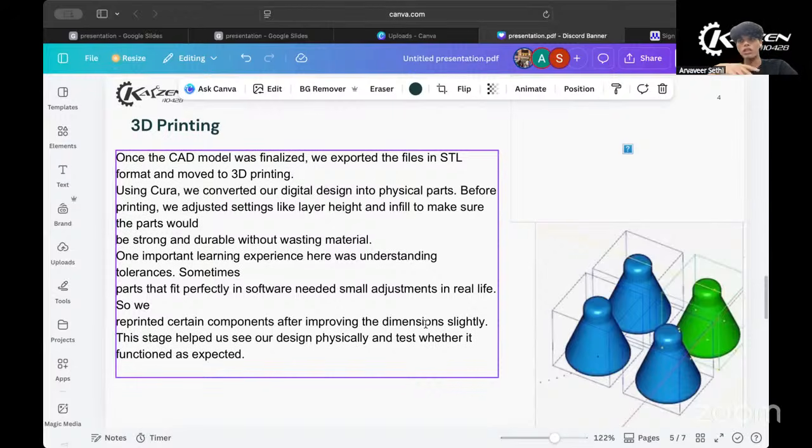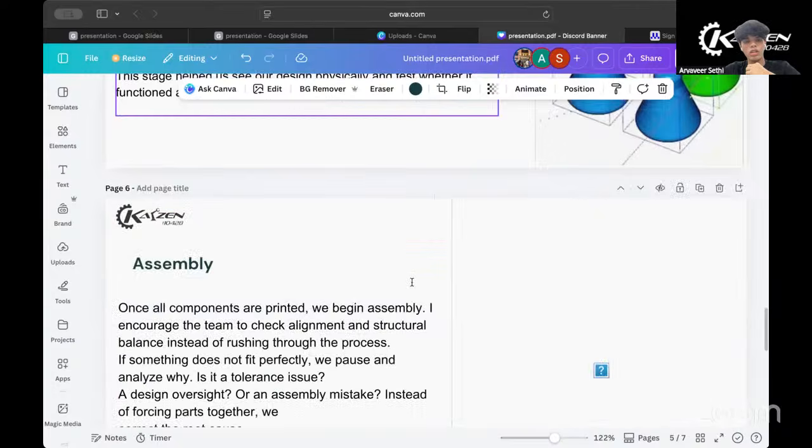Another thing you can customize is the pattern of the infill. You can have hexagonal patterns, net patterns, tetrahedral patterns. Each pattern has a different use. For example, hexagonal patterns give you more stability, and something like a web pattern makes the part able to bend more and contort its shape more. Different use cases require different shapes. Now we'll move on to assembly.